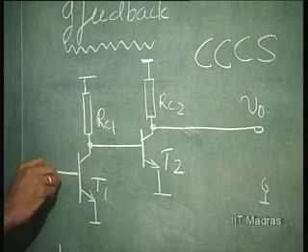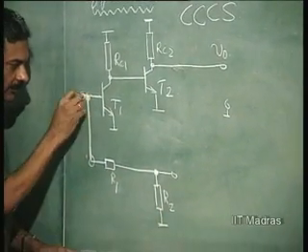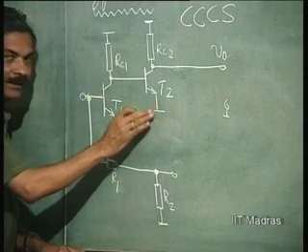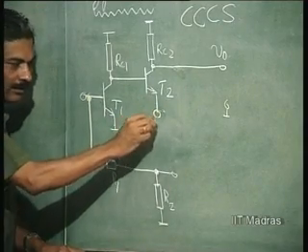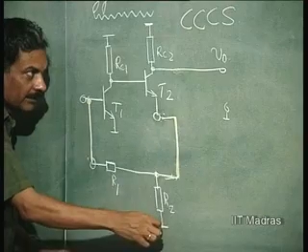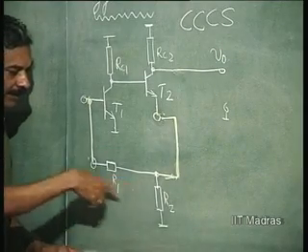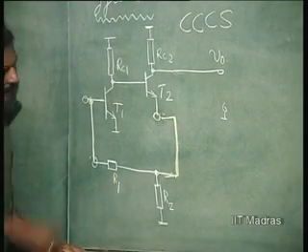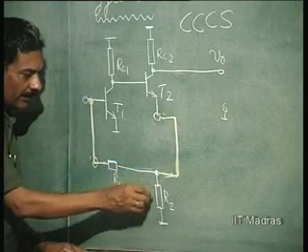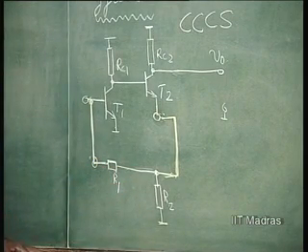Things should be in shunt at the output. So, this is the feedback network, it is in shunt at the output, common, right, voltage is common to both, and in series at the input. That means, I lift this and connect it together, lift it and connect it together in series. So, the output current is common to both, right, here for the feedback network and now. So, the feedback network remains the same, R2 and R1. The current here is going to be taken and is going to get divided based on this kind of relationship between R1 and R2.